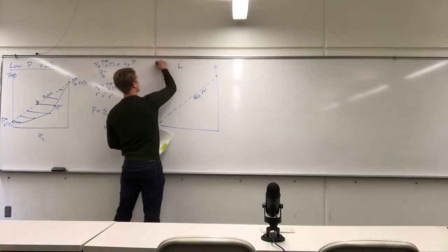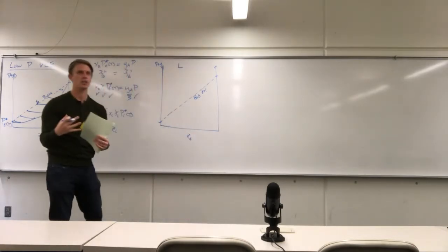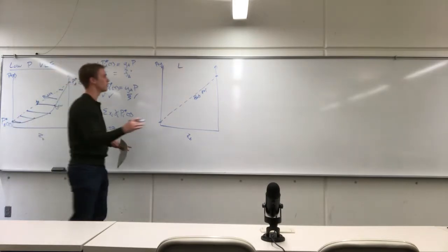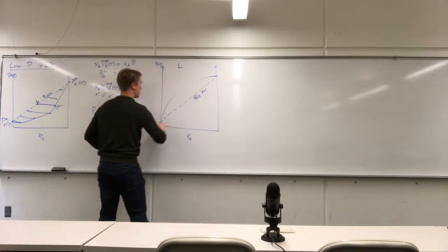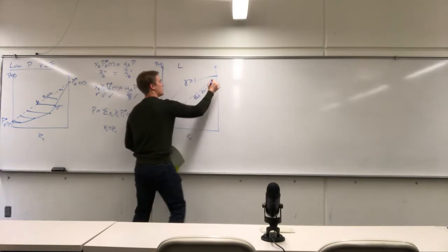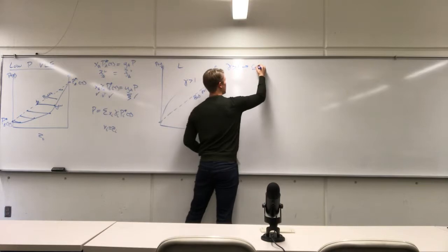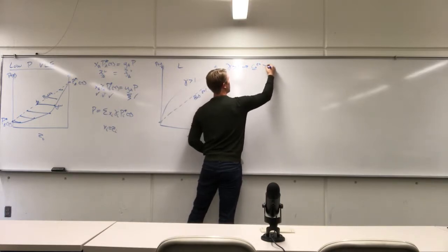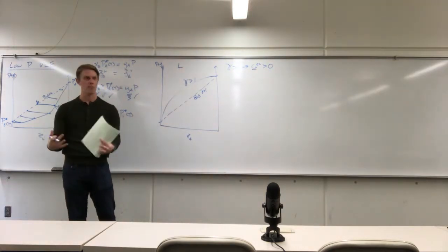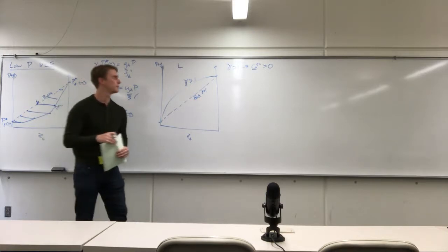right, at high pressures we have a liquid. If the fluids don't like each other and there's non-ideality in the liquid phase, they want to get away as fast as possible, meaning that you're going to have positive deviation from Raoult's law behavior. This is going to be activity coefficient is greater than 1. Now, if activity coefficient is greater than 1, that means that the excess Gibbs of the system is going to be greater than 0. Low Gibbs means happy fluids. High Gibbs means unhappy fluids.